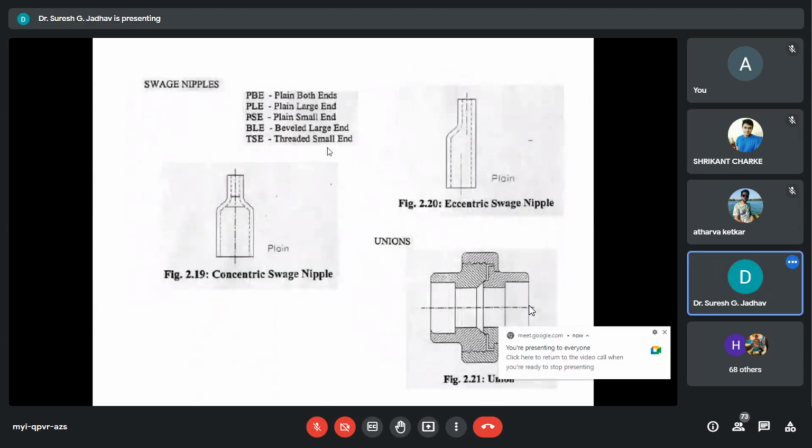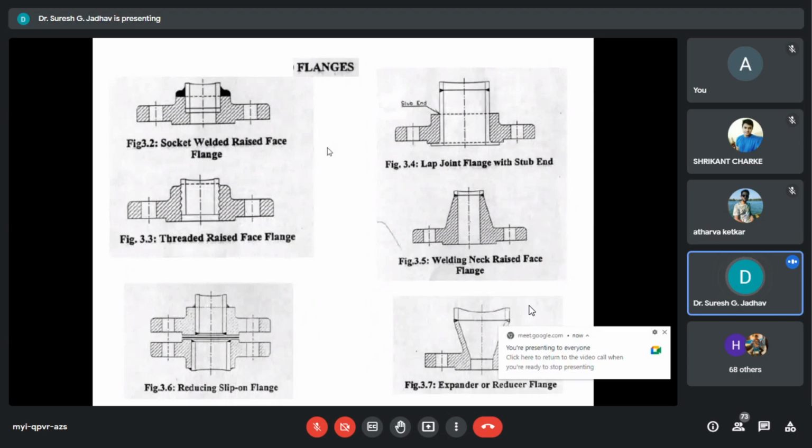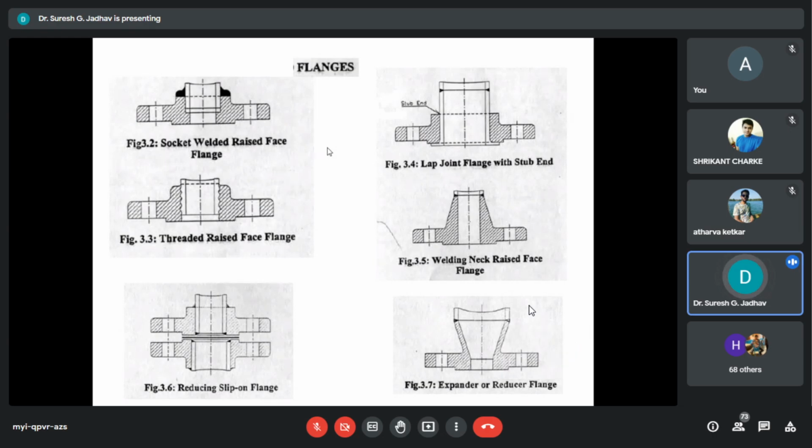Flanges, we are discussing different kinds of flanges. Flanges are used when a joint needs dismantling. These are used mainly at equipment, valves, and special fitting components. In certain pipelines where maintenance is a regular feature, breakout flanges are provided at definite intervals on pipelines.